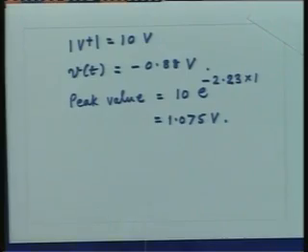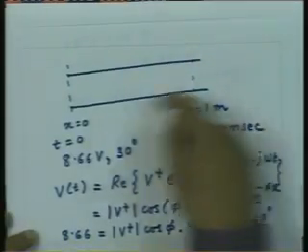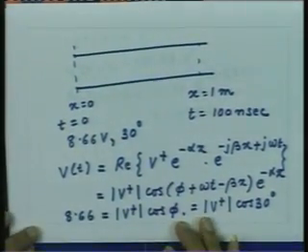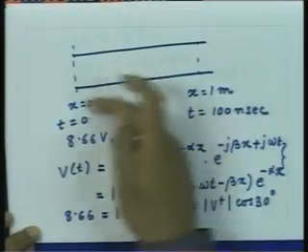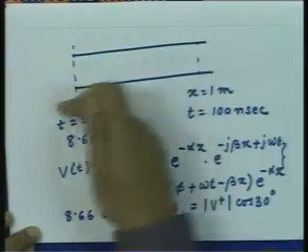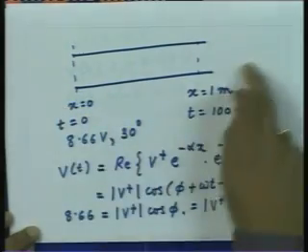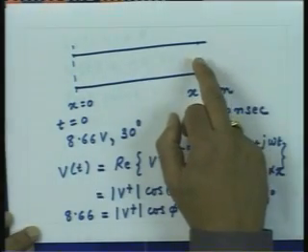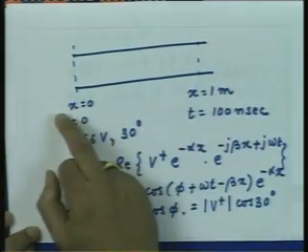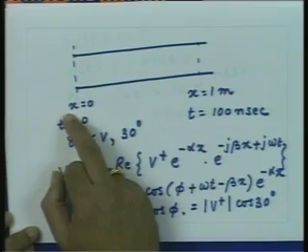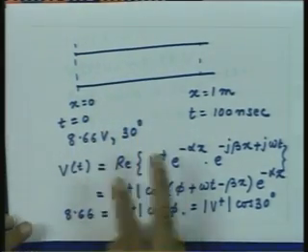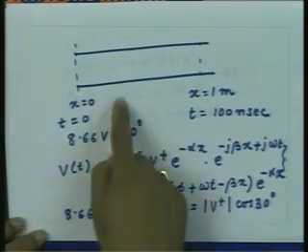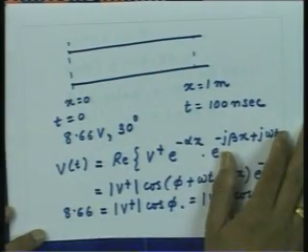If I take the other situation where the wave travels from right to left, then its attenuation is from right to left. That means if I work backwards, I know the wave amplitude at this location, and its amplitude at this other location will be more compared to the amplitude here. So, when the two waves are traveling in different directions, and alpha is positive, their amplitude behaviors are not the same. The wave always attenuates in the direction of propagation.